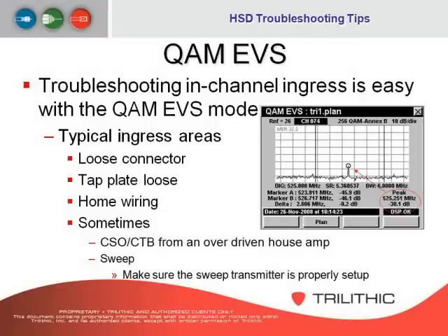So what you can do is use the QAM EVS, and when you're using the QAM EVS and the H60 DSPI, the meter mathematically removes the haystack from the display, allowing you to see the noise floor under the signal. Like in the example here, it shows that the QAM analyzer's peak marker is auto-placed on a beat at minus 30.1 dB. It's actually below the actual QAM carrier, and then it also depicts what the frequency is of where that beat is.